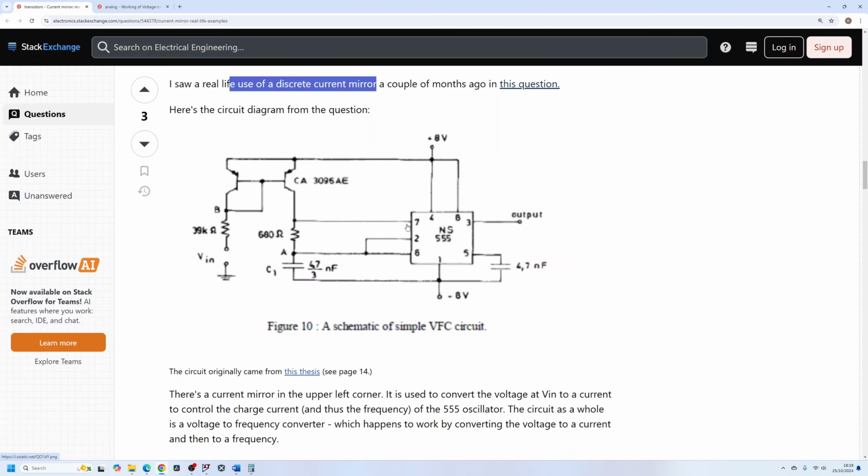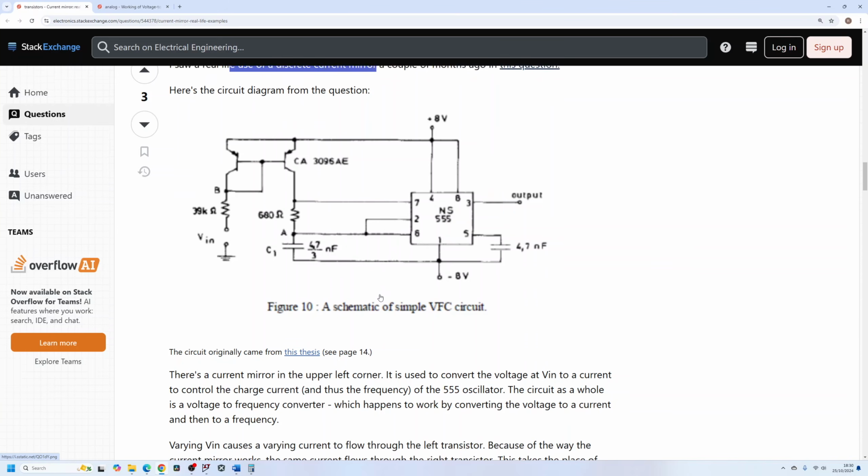I've not used a 555 timer for a very long time, but you can see that this capacitor is going to charge at a fixed rate. You set up a current over here, and the current going through this resistor and into this capacitor is going to be fixed. You basically negate the capacitor charging curve, the exponential, and you can get a linear line with a fixed input current, I think anyway. I'm just analyzing that off the top of my head. If you were to draw this out, I think the voltage on this capacitor would look like a linear line rather than your typical capacitor charging curve. But I'm not entirely sure on the pinouts for this 555 timer, but it's an interesting application, and maybe you can simulate it in LTspice as well to see how it works.